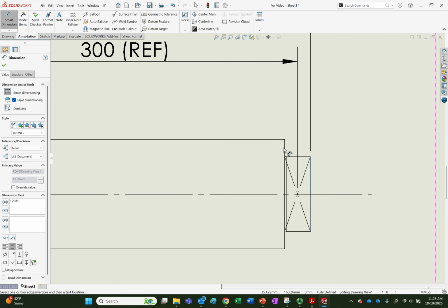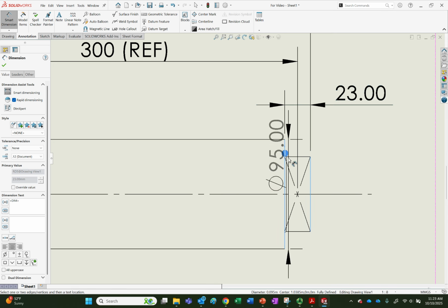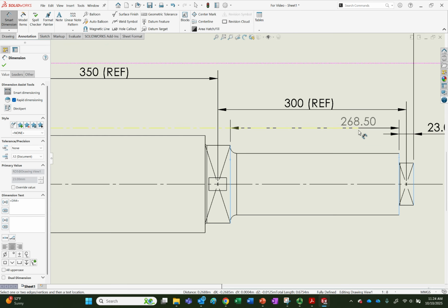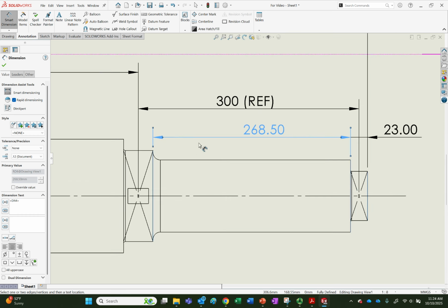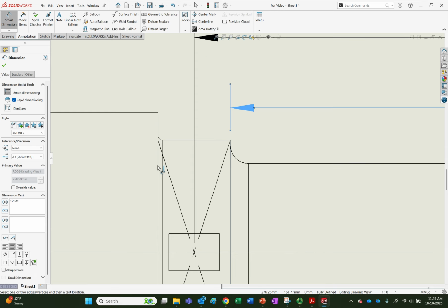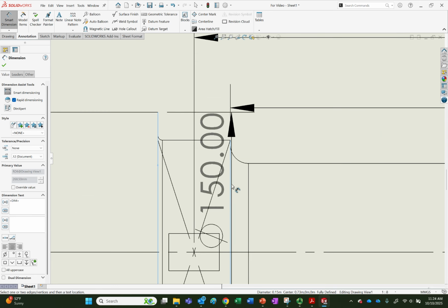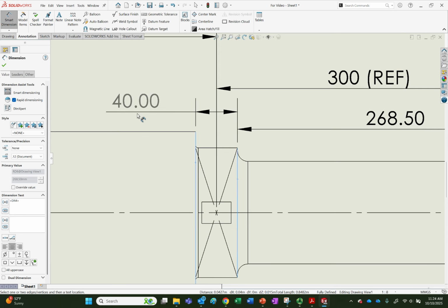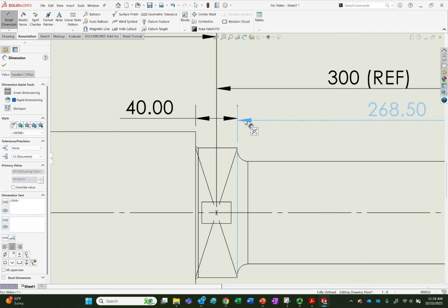I'm going to go ahead and dimension off this way right here and do the same thing. You could have put TYP next to a dimension if it's the same dimension in multiple places, but there's only 2 places, so it's fine. I think you can tell from that that's the dimension you want. And then finally that to, well, I don't feel like I'm grabbing it to that. Yeah. Okay. Got it. These would be a little bit higher up to line it up. Boom, boom.